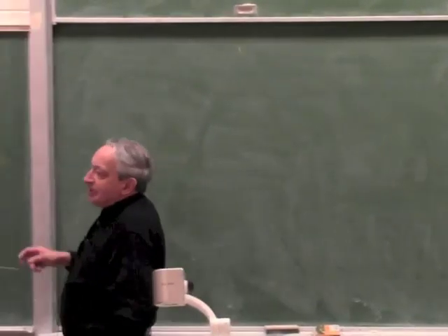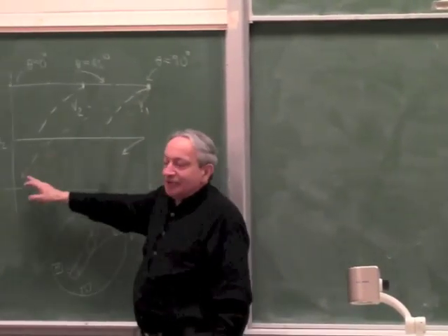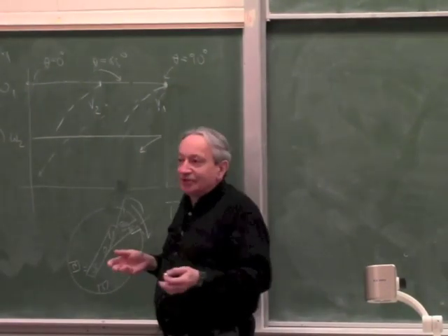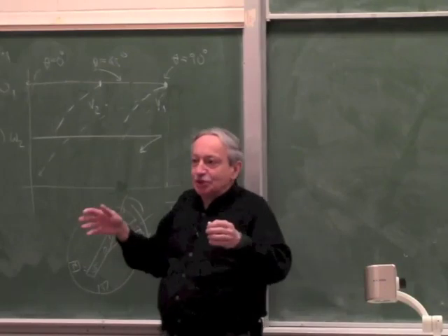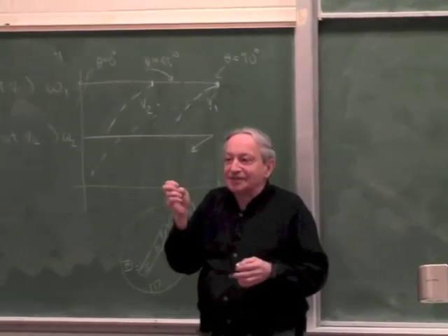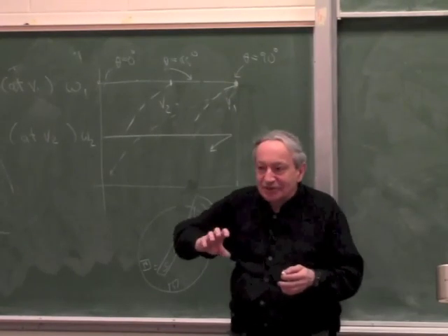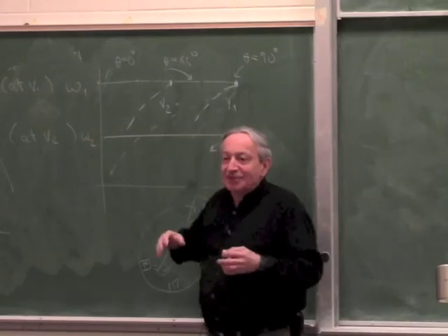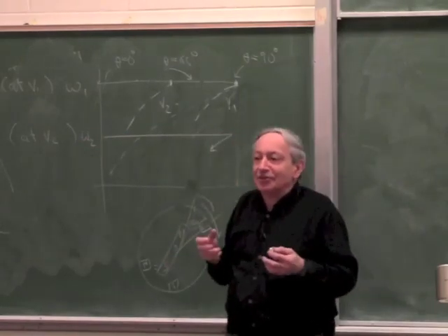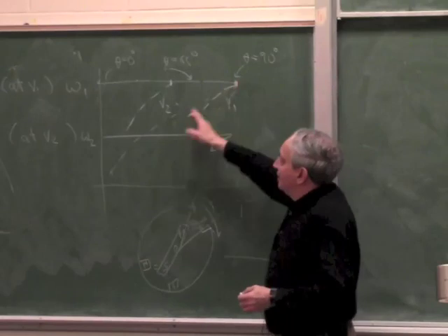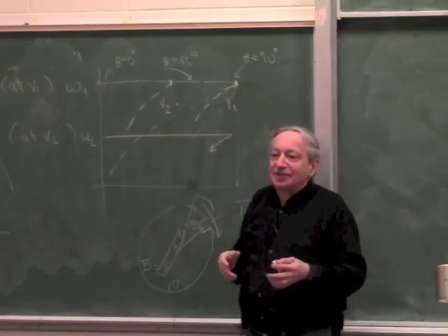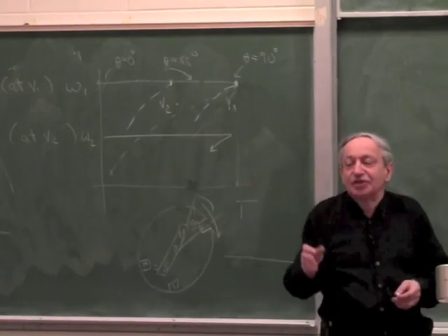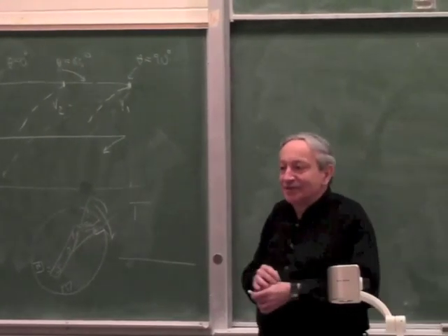Now, I'm reminding everybody, the reason why this is very undesirable is when you start a motor, you always exceed the rated torque. Because when you start a motor, there's inertia. So the very first few milliseconds, the inertia doesn't allow the rotor to move as fast as the rotating field wants. So when you start the motor, the first minute, there is always a high torque. So if this motor collapses at a high torque, it doesn't want to start with any inertial load. And that's, as I mentioned, the only disadvantage of synchronous motors. They have no starting torque.